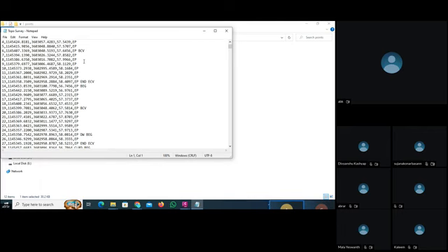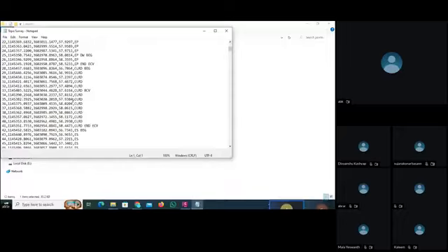So when we create a group, we give the name as building. Then for the building, my surveyor set a description code as BLD. Then for the center line, they set a code as CLRD. You can see here, first of all, you see EP. EP is also for the center line. DW is also for the center line. CLRD is also for the center line.